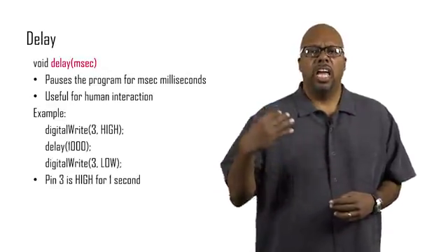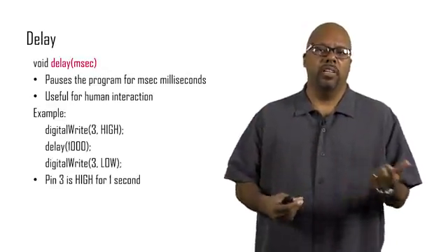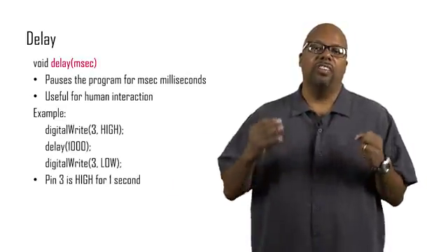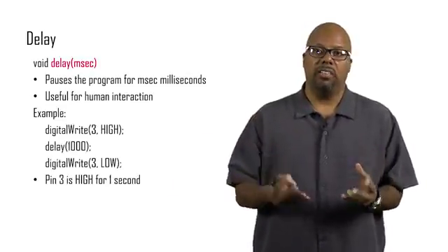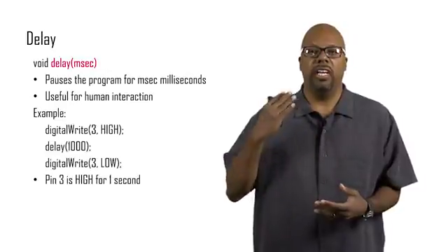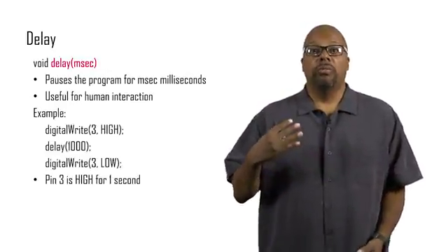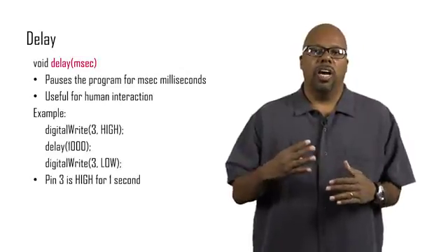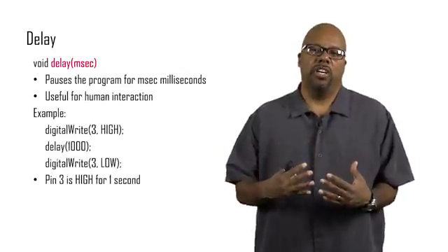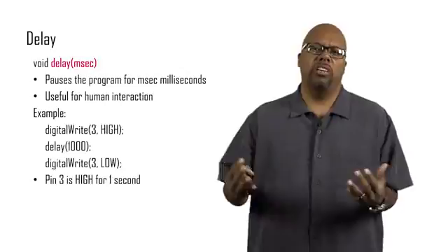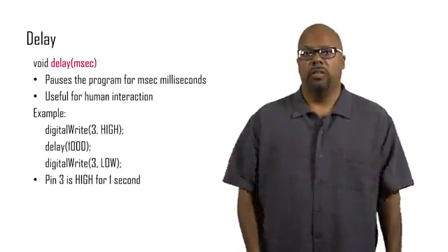You can't just output some data and expect the human to read it in one clock cycle and then change it. If you want the human to see something, to hear something, it has to be present for a certain amount of time, or else the human can't even perceive it. So you get this problem a lot where you have to delay things inside your microcontroller just so the human can properly perceive whatever it is you're trying to give to the human.